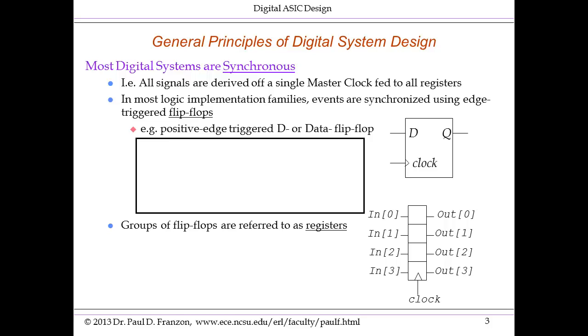So most digital systems are synchronous, and all the digital systems we're dealing with in this class are synchronous. That means that there is a master clock fed to all the registers, for the purposes of this set of notes, one clock only. And edge-triggered flip-flops are triggered by this master clock to synchronize all logic. And also it's useful to think of these flip-flops as storing those logic values between clock periods during which logic is re-evaluated. But let's just deal with the flip-flops first.